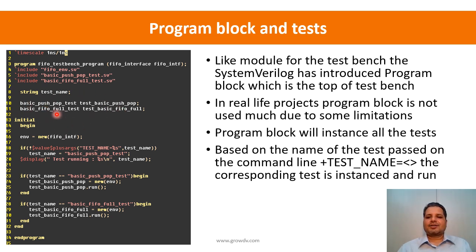We will see what these tests are. Tests are actually classes. We will see how they are implemented, but for now just understand that for whatever tests we have included, we have created a handle for each of them, and then we have this one initial block, and inside that we are first instancing our environment, right? So we have instanced our environment, and then if you remember, as a part of the Verilog refresher, we had looked at this system task called